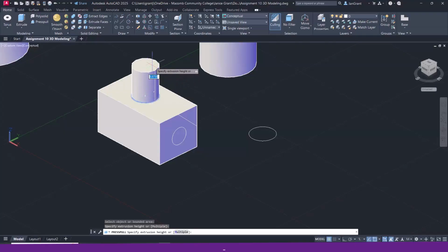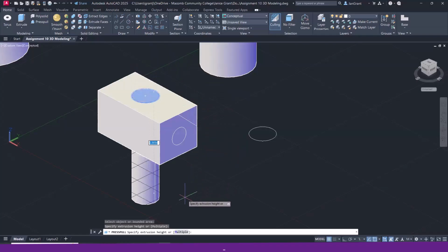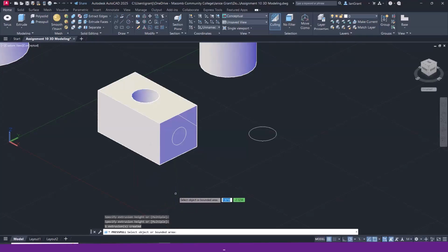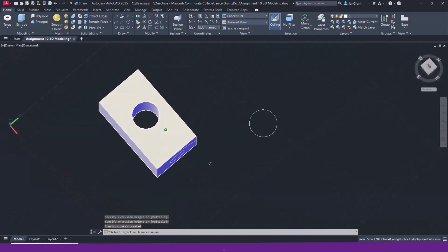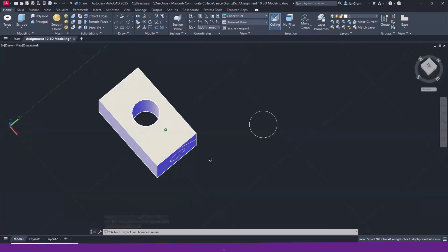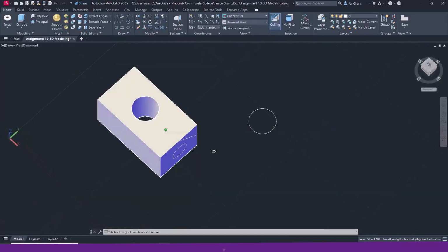right here and click. Now, if you pull your mouse away from the other solids, it will create another solid that automatically unions these two together as one piece. But if you pull your mouse all the way down inside the solid model, all the way down to the bottom, and then click, you see how it makes a hole? So I'm going to hold my shift key and the wheel of my mouse. I'm going to look in this hole. Look at that. So press pull will help you to kind of reshape your model.